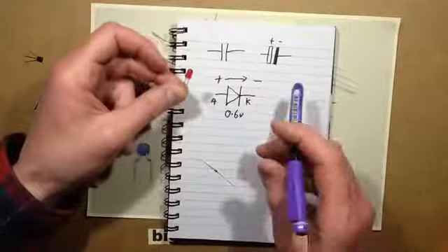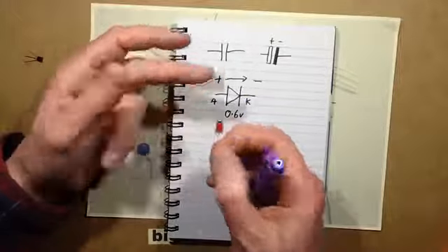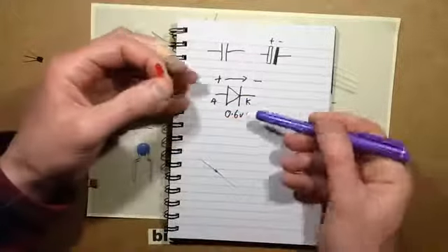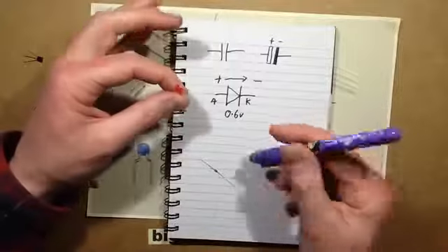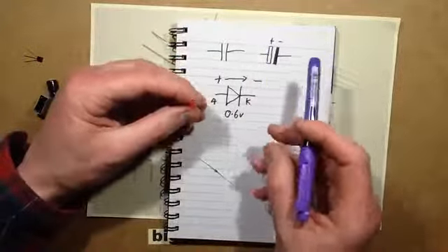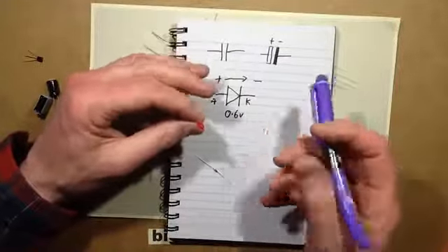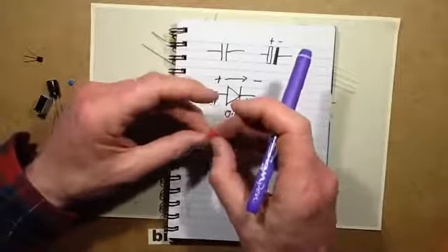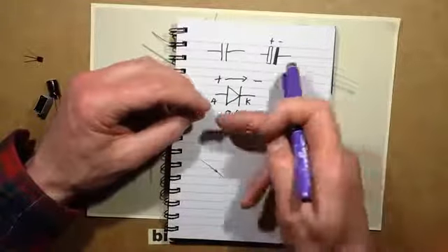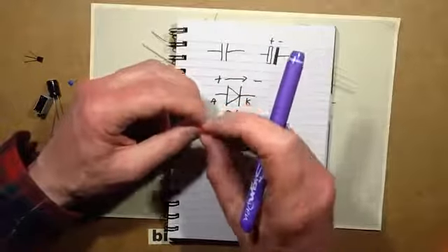But one of the things you have to note with an LED is that, because they're optimized for emitting light, they don't have a high reverse blocking voltage. It's usually just about 5 volts. So if you were to connect the polarity wrong and exceed about 5 volts, then in the case of white, blue, green LEDs, it may damage them, but with red ones, they may end up just conducting in the wrong direction, but not lighting, and not suffer damage.